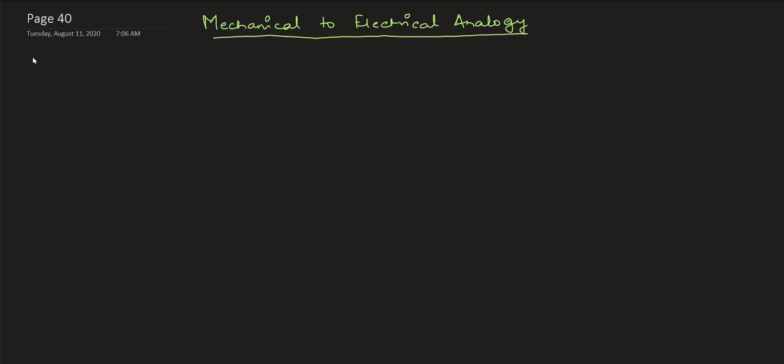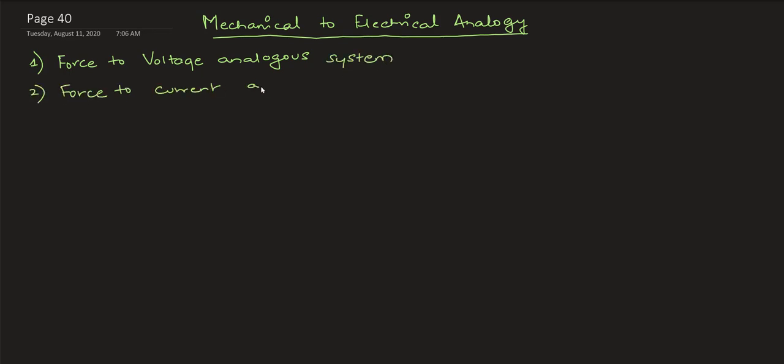So now I am just writing here, if the question says you need to find theta 1 of S upon T of S, then you can also do the same thing. You need to substitute theta of S from 6 and 3. So the question can ask for the transfer function in terms of theta 1 of S or theta of S. It doesn't matter, because in both cases you're going to do the same substitutions, except the variables are going to be theta 1 of S and theta of S.